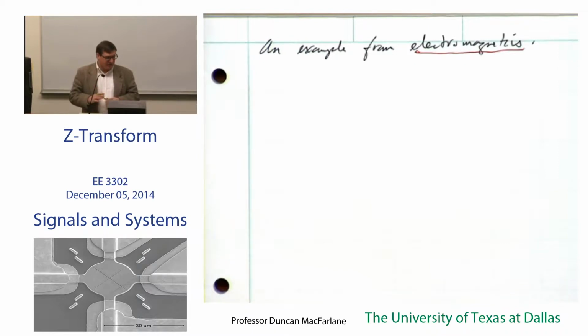So let's just think a little physically. The example that I'd like you to have, I think, you've worked with in the laboratories upstairs, where you've worked with the function generators and the oscilloscopes, and in particular the coaxial cables that connect the two. So what I want you to think about for a second is lambda nu, or lambda f, is equal to the speed of light. And the speed of light c is 3 times 10 to the 8 meters per second. It's just a touch slower in those coax cables. The signal moves down those coax cables at about 2/3 the speed of light.